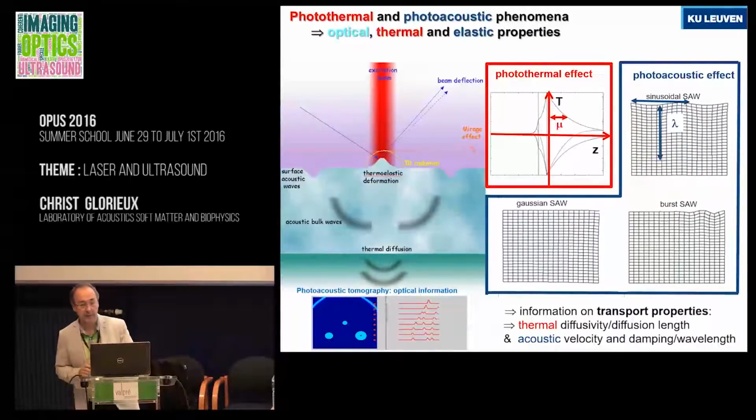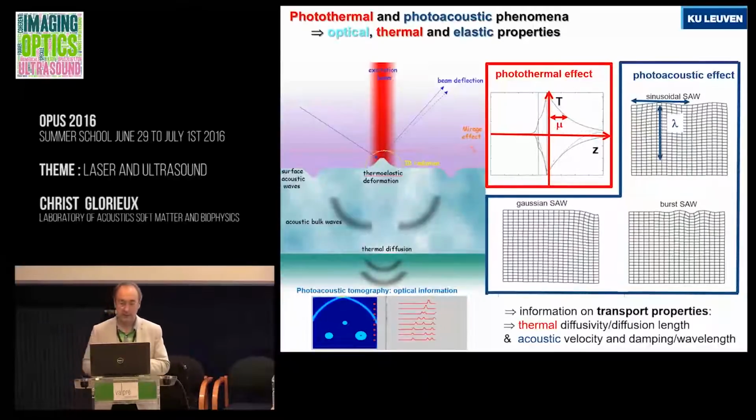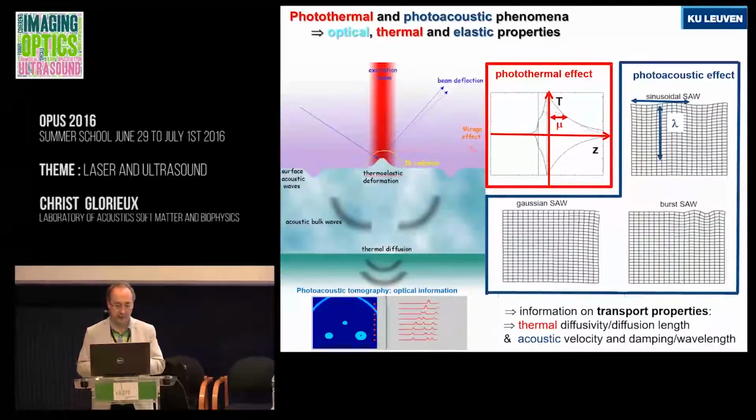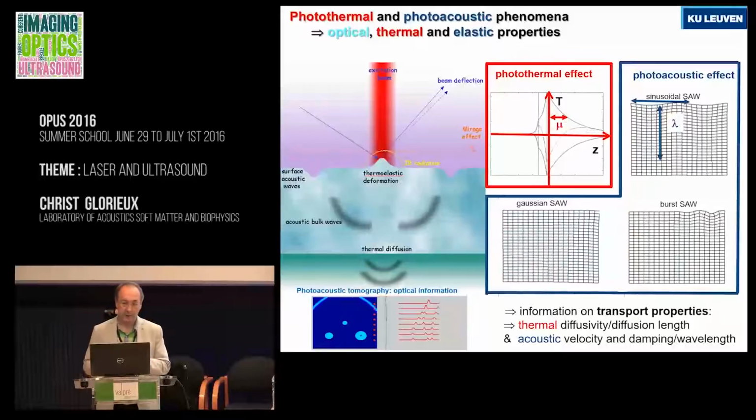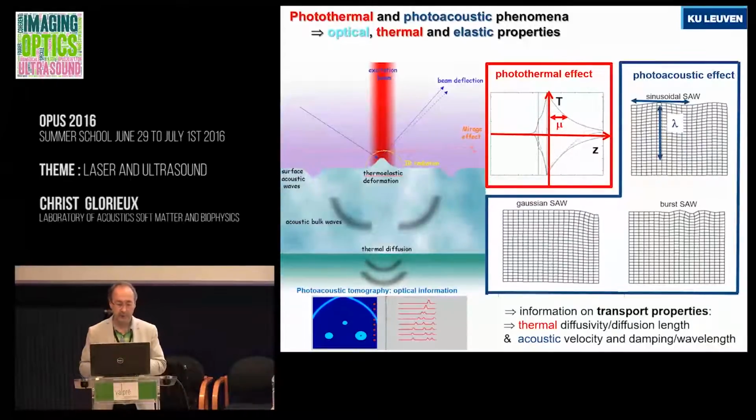At the same time, if you modulate fast enough, you have efficient acoustic excitation, and with that you can make all kinds of acoustic waves. In our lab we are focusing on guided waves, and more in particular surface waves, which become plate waves when you have a thin sample. The nice thing about surface waves is that you excite them at the surface, and they have a certain range of penetration.